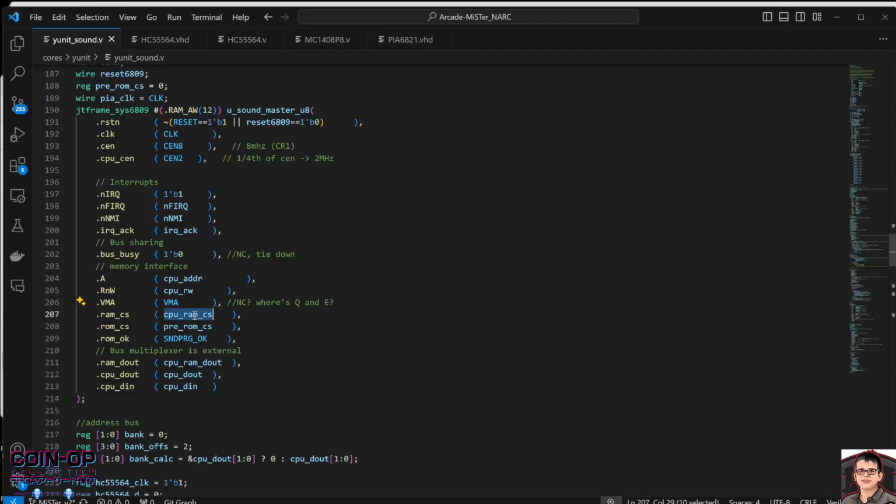And then you have RAM select, ROM select. That'll tell it, since this wrapper is managing the RAM and also requesting to ROM, and it uses that to track the recovery too, like the recovery it should apply, if it should recover cycles or not. Then you need to tell it when it's RAM or when it's ROM, and also supply the OK signal for the ROM so it knows exactly how much time was spent to retrieve that, and it compensates and does recovery of the cycles properly. Okay.